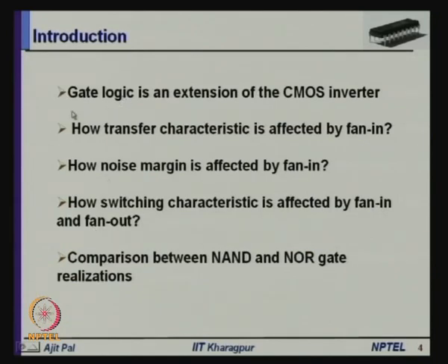and we shall see in this lecture how different types of gates, particularly NAND and NOR gates, can be realized by extending the basic concept of the CMOS inverter. Whenever we are making a NAND or NOR gate, essentially we are increasing fan in. I shall elaborate on what fan in is and how the transfer characteristic is affected by fan in, that we shall discuss in detail.